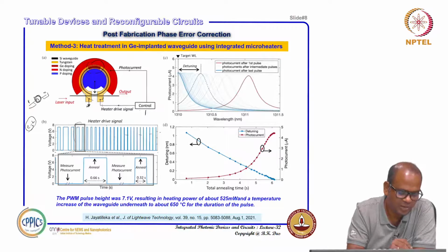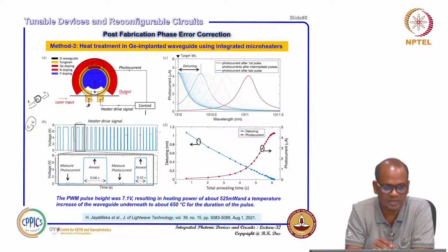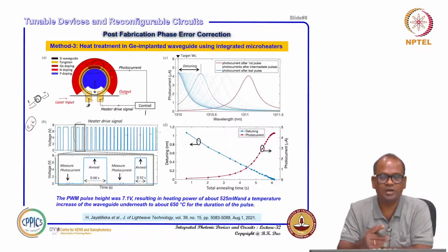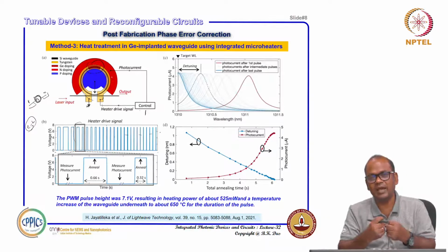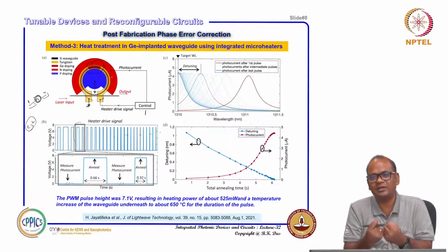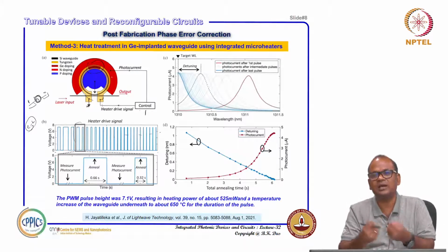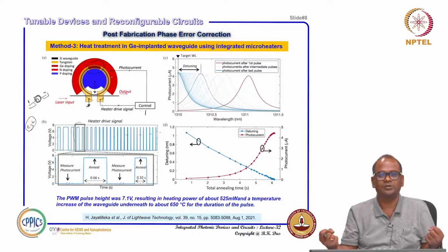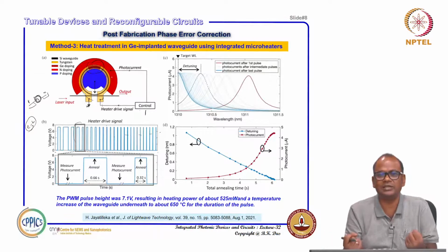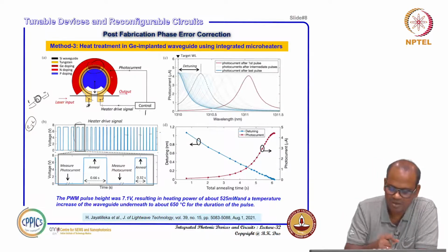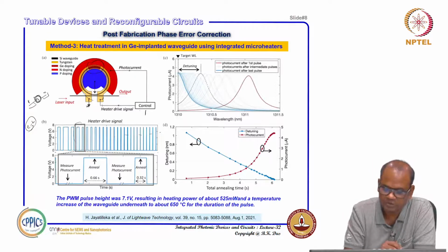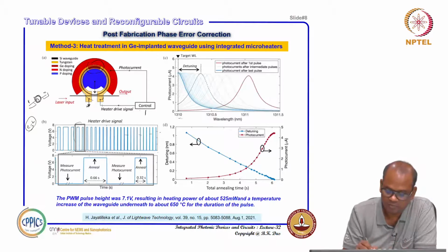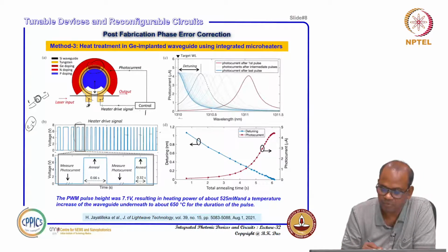When an electron hole pair is created, you already have the p-n junction here. If you give a reverse bias, you can actually extract the excess carriers generated, and depending on the carrier density, you can see the current flowing across the waveguide. So depending on the current, you can actually measure the intensity inside the ring resonator. Okay. So for example, it is shown here. If you just detune the wavelength from 1310 to 1311 nanometer, right.